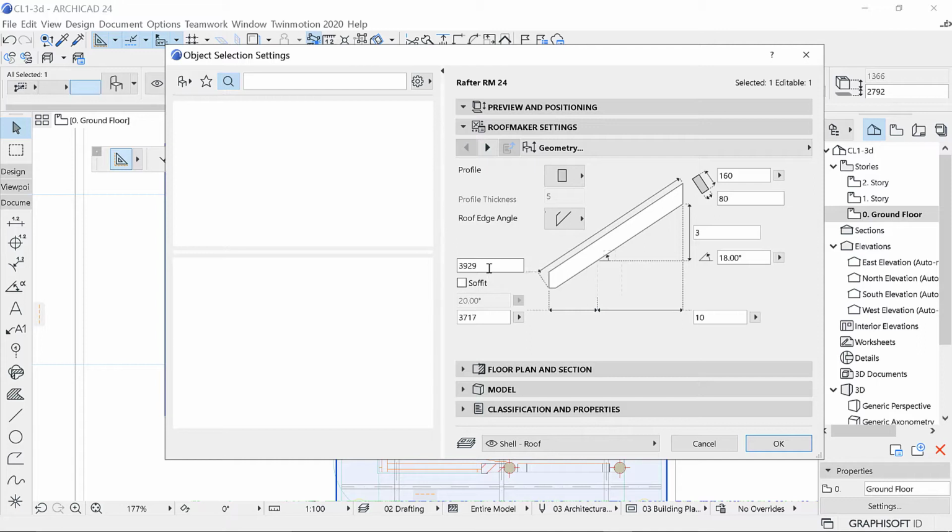Earlier on, if you've determined the sheets before, you know, I'd said we are going to use the default ones, which are 2 meters, 2.5, and 3 meters. Those are the three major types of sheets. But nowadays you can also buy the ones which are measured per meter. In this case, you can see how many pieces you will need. That's the length of the sheets.